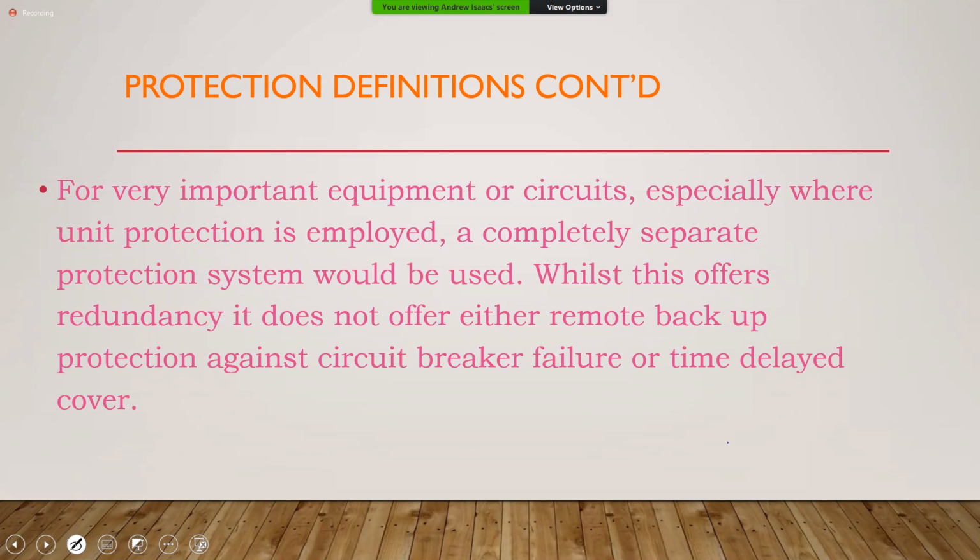As a matter of fact, that's another name that the relays have. So some relays require both a voltage and a current input to operate. And the voltage output from your VTs is a standard 110 volts phase to phase.